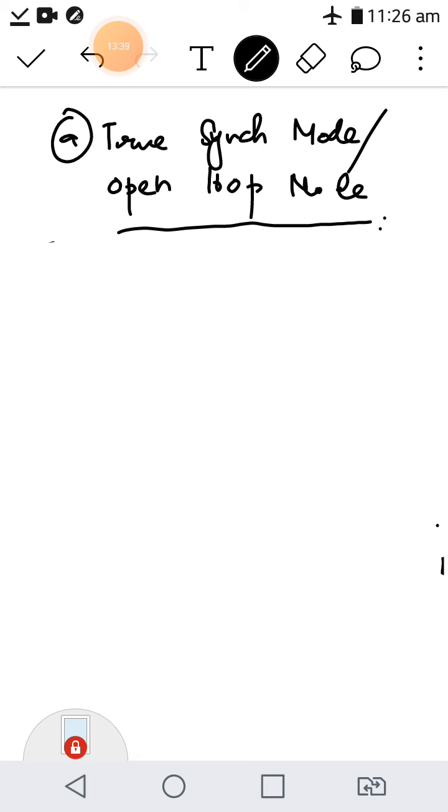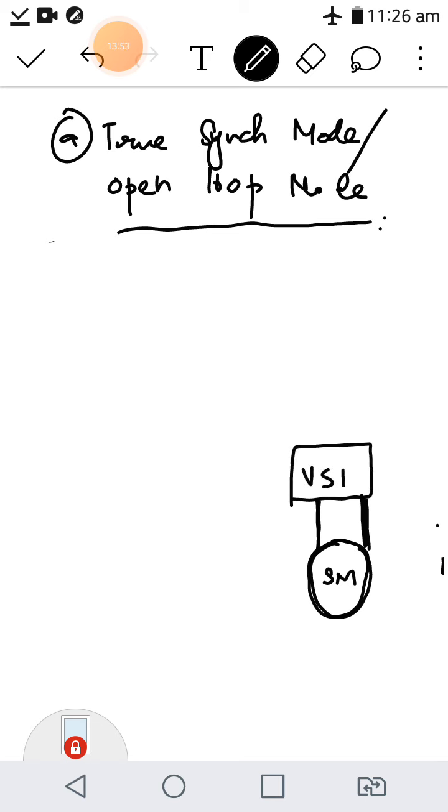You have a synchronous motor. It's fed by a DC. The stator of this machine should be supplied with a variable frequency and voltage source. So for this source we can use a VSI to feed that stator. But VSI is an inverter. Its input must be DC, output is AC.